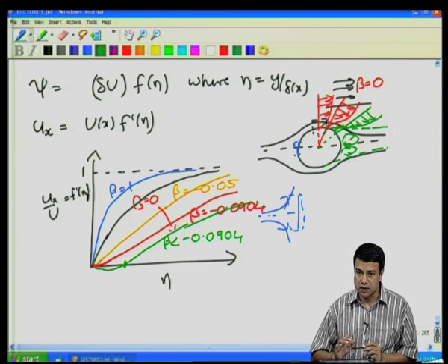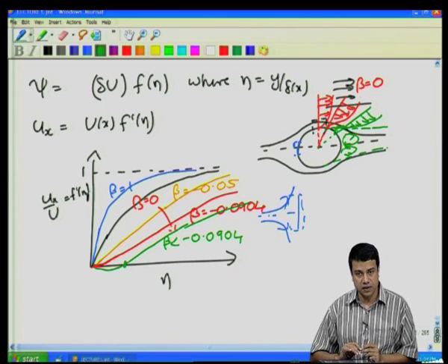The boundary layer theory is telling us that when the flow decelerates on the downstream side of the cylinder, there is boundary layer separation, and the potential flow solution is no longer valid. There is a wake region at the back where there is recirculation. In this recirculating region, the pressure is much smaller than it is on the upstream side of the cylinder, and for that reason you will have a net drag force. Objects in which there is boundary layer separation at the back are often called bluff bodies.